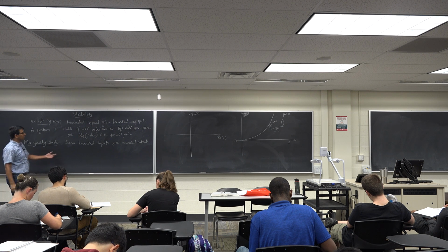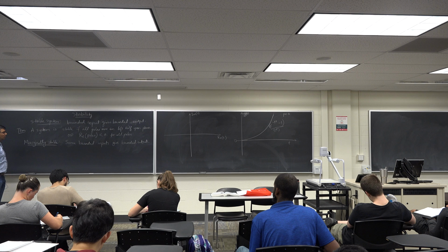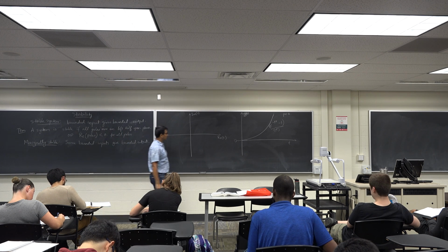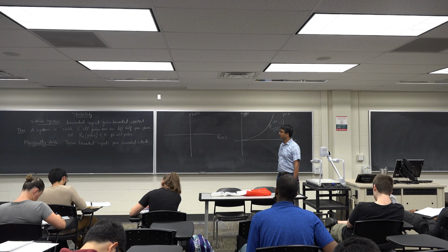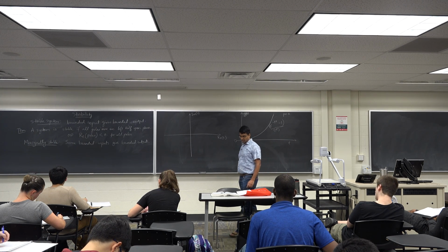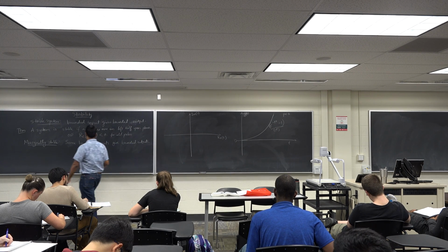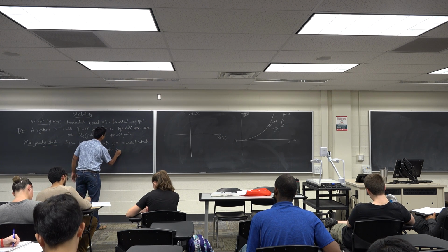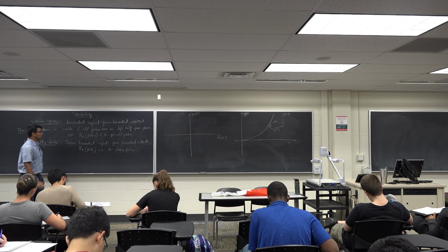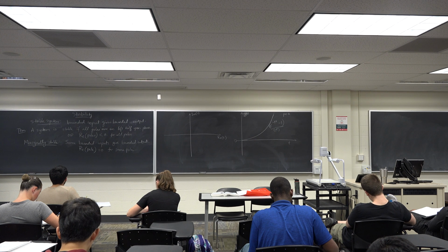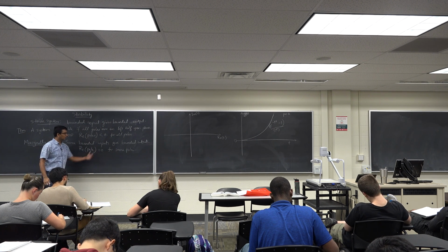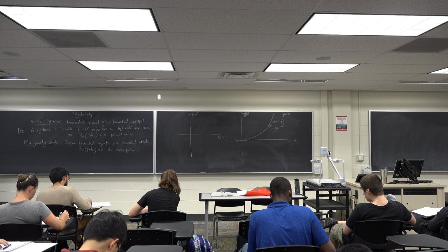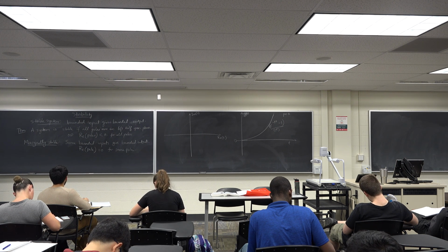So a system is marginally stable if some bounded input gives bounded output, while other bounded inputs could give unbounded outputs. So that's known as a marginally stable system. This happens when the real part of some pole is equal to 0. Even if you have a couple of poles with real part equal to 0, it will lead to a marginally stable system, which means for some bounded inputs it will give you bounded output, and for some bounded inputs it will give you unbounded outputs.